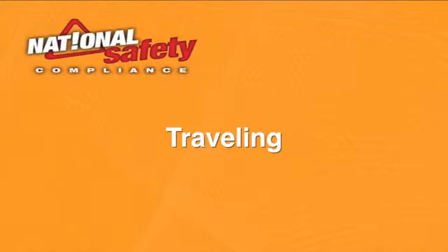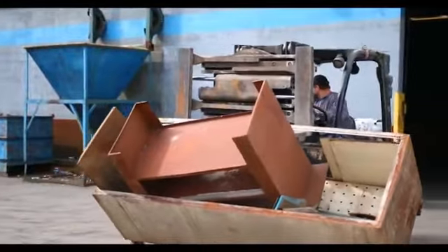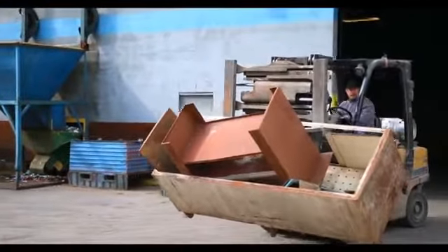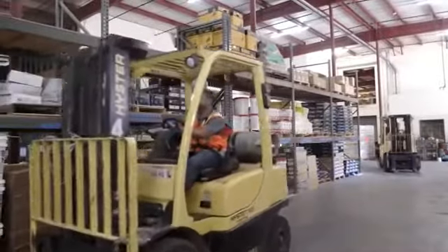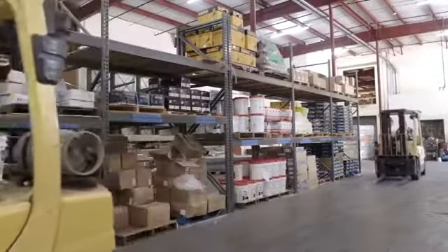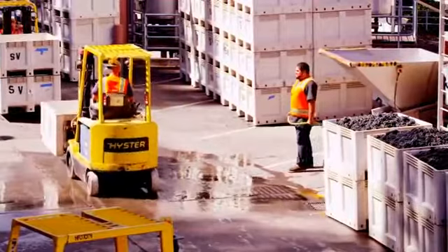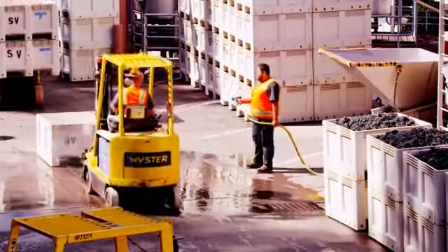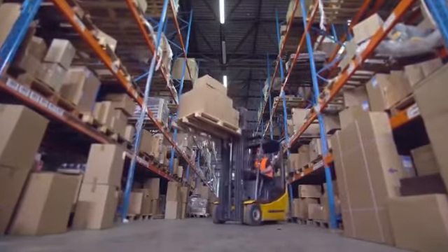Traveling. Forklifts should be operated at a speed which allows for stopping in a safe manner, avoiding tip overs, and avoiding collision with pedestrians and obstacles. Always maintain a safe distance between forklifts, approximately 3 truck lengths. Slow down and sound horn at cross aisles and other areas where view is obstructed. Slow down on wet and slippery floors and avoid driving over loose objects. Look in the direction of travel, always keeping a clear view.